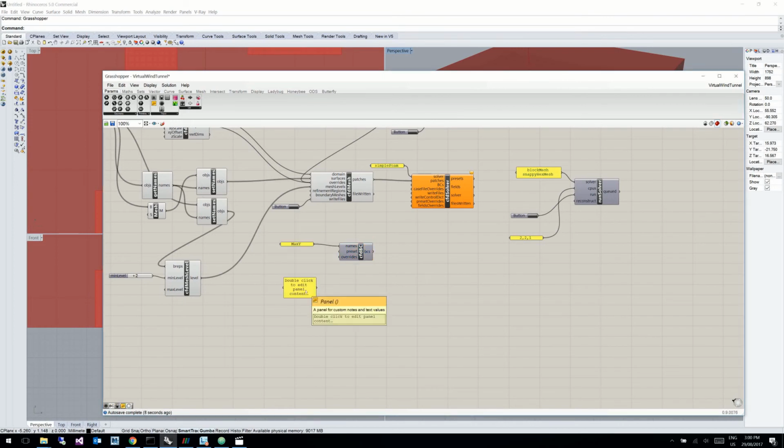We'll use a preset condition in this case. I'll explain what these presets are in a little bit, but for now, let's just use a preset of fixed velocity. Fixed velocity by default just defines a null velocity or 0, so we actually need to override the fixed velocity definition with U is equal to value uniform (0 -5 0); Don't forget to end with a semicolon. This is just a standard dictionary override definition, which we'll talk about later.